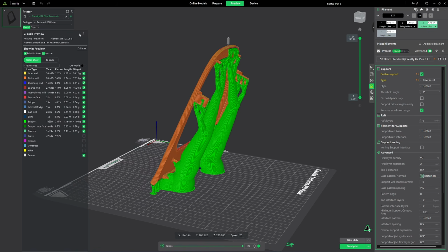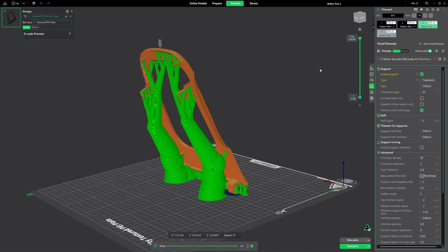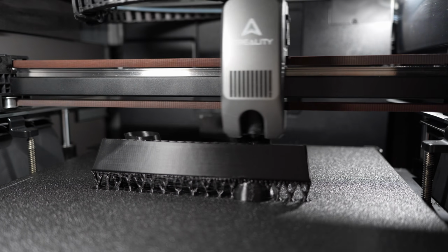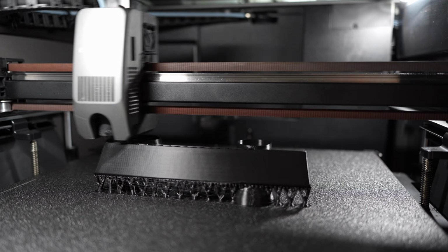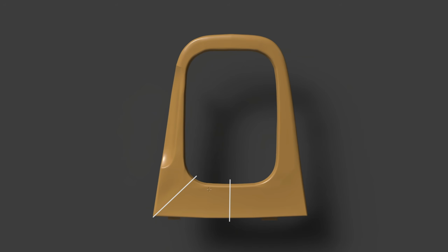At the end of the video, I will also 3D print this part to see how it looks and feels in real life. The approach I will use to model this part is with the Loft command. I will crop the point cloud into a thin slice and then create the sketch profile along the cross sections, which are shown here with the white lines.